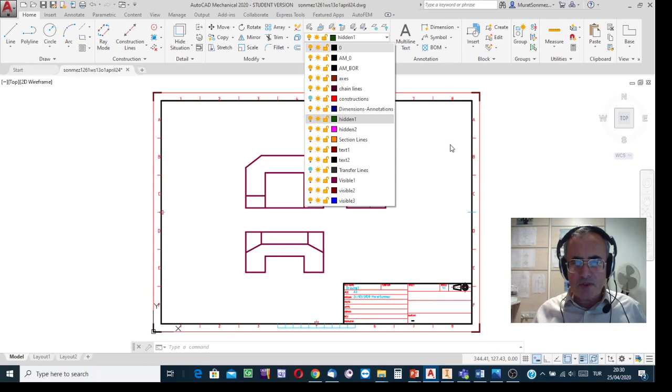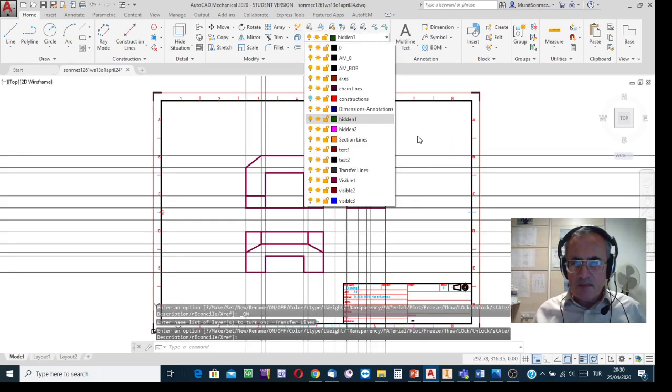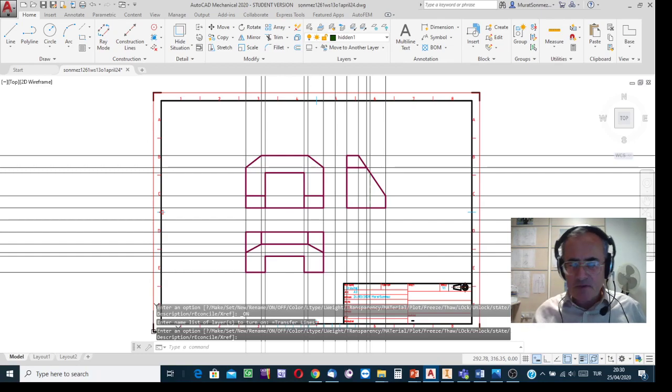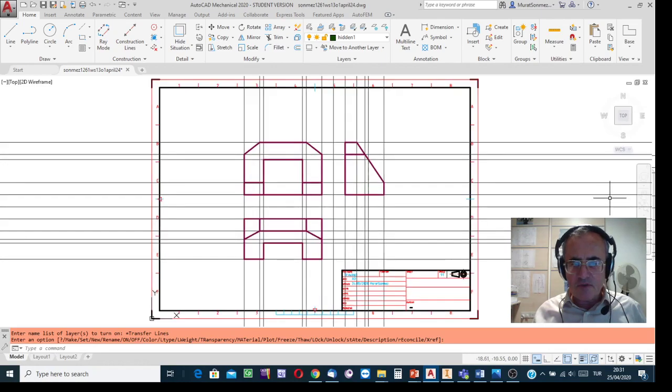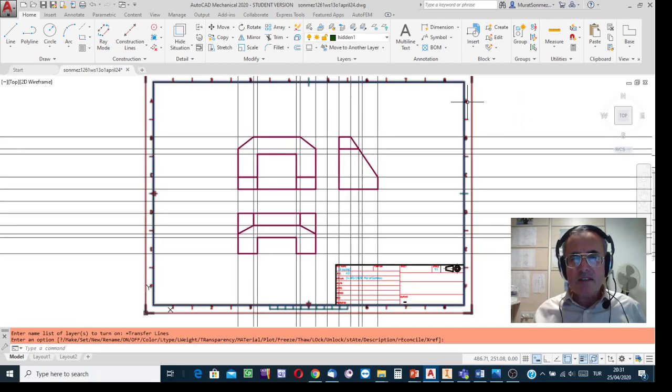For multi-view projection, remember the things from the previous class work. It is sufficient to talk about how the multi-views are drafted using the two-dimensional part of AutoCAD. Well, we mark the images of the characteristic points using transfer lines.